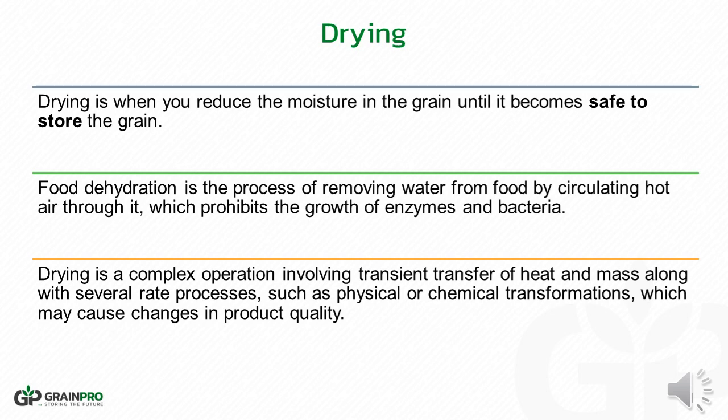Due to temperature and vapor gradient from the surroundings and the commodity, the water from freshly harvested wet grains is carried by the heated air. This process of heat and mass transfer is further enhanced by a blower, which allows the moist air to move faster through an outlet.